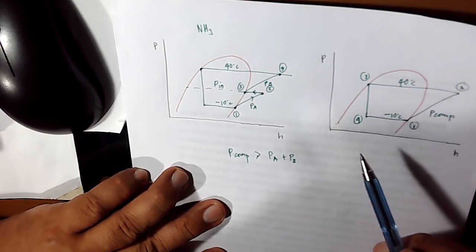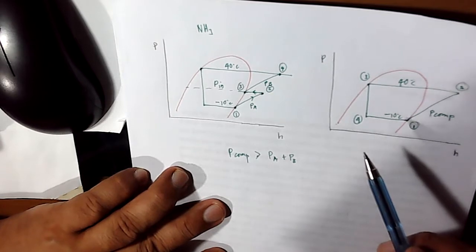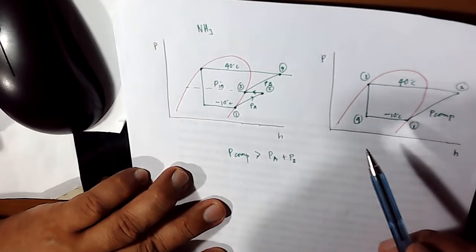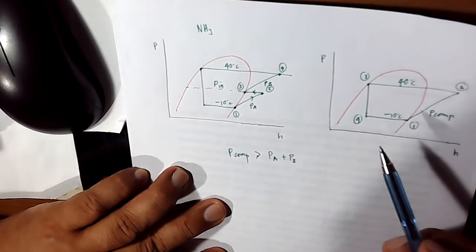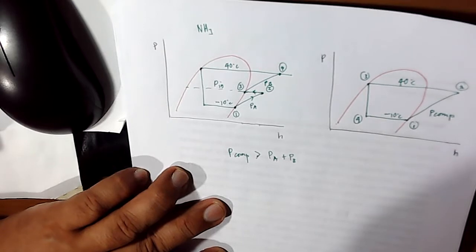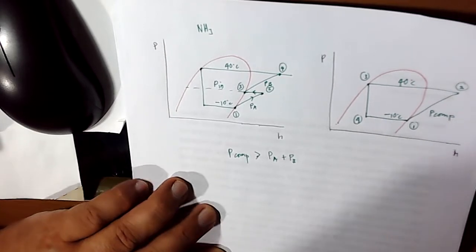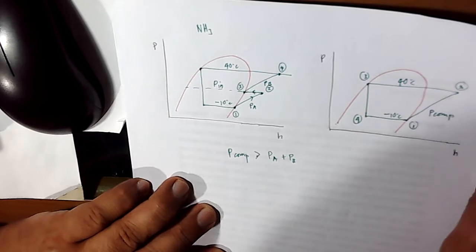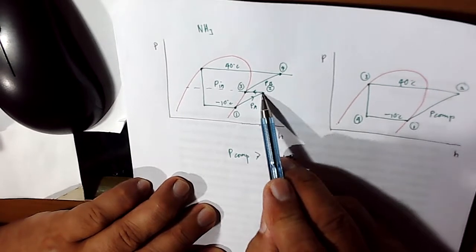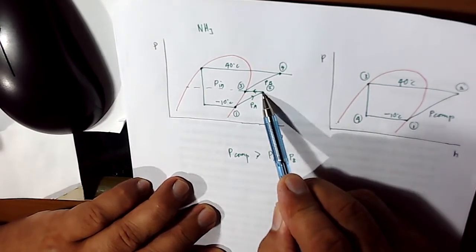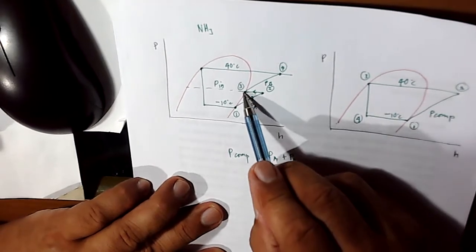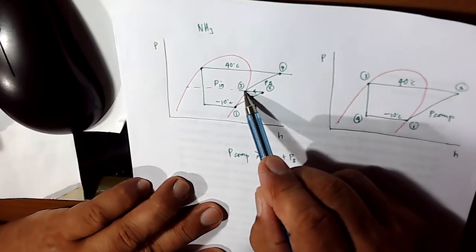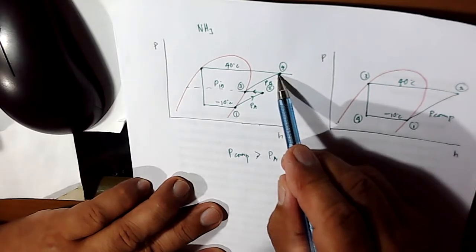Okay, there will be a power save in compression, or reduction of torque of compression per pound of vapor. When we combine these two, notice that point 2, using the intercooler, the water-cooled heat exchanger, will automatically go to the saturated vapor line before it goes to the second or higher stage compressor.